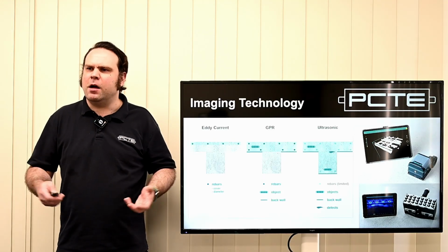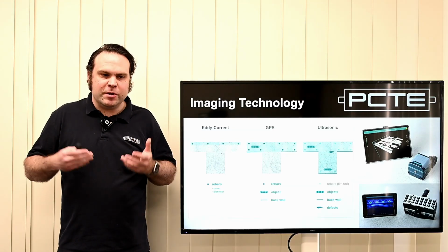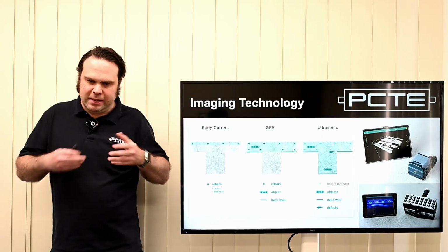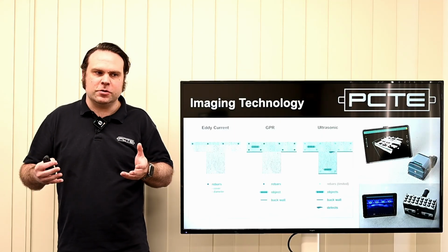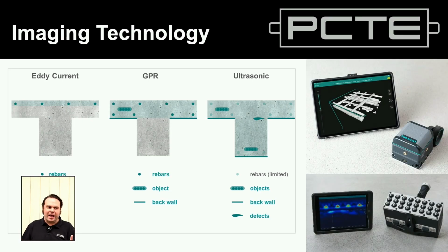And when we go to radar, we've got some sensitivity to non-metallic and some geometry measurements. But if we're looking for voids or defects, typically something air or cracking or damage to a structure, we'd be more likely to go ahead and use the ultrasonic tools, which is what we're going to cover on the last session of today's presentation.